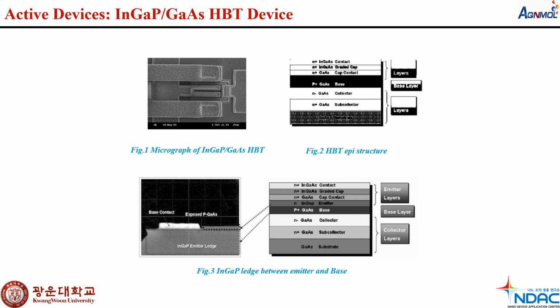In this section, for the active device, we will focus on indium gallium phosphide gallium arsenide HBT devices. The high linearity, in short HL, process active device is so named because of the intrinsic device linearity of the indium gallium phosphide HBT, which is the result of uniform current gain characteristics. In turn, the gain characteristics are a function of collector current, the independent collector capacitance and the high Early voltage. The thermal conductivity of gallium arsenide is lower than silicon. Therefore, when the MMIC is designed using an indium gallium phosphide gallium arsenide HBT, the self-heating effect must be considered.